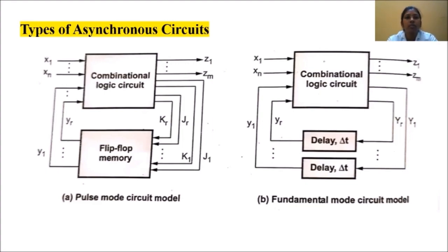In order to ensure proper operation, it is necessary for the asynchronous sequential circuit to attain a stable state before the input is changed to a new value. Because of the unequal delays in the wire and gate circuits, it is possible to have two or more input variables change at exactly the same instant. Therefore, the simultaneous changes of two or more input variables are usually avoided. In other words, only one input variable is allowed to change at any one time, and the time between the two input changes is kept longer than the time it takes the circuit to reach